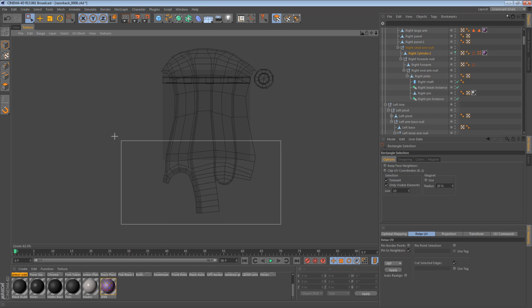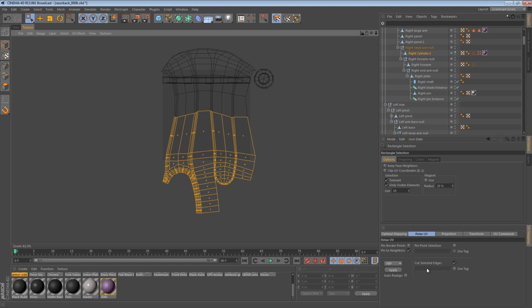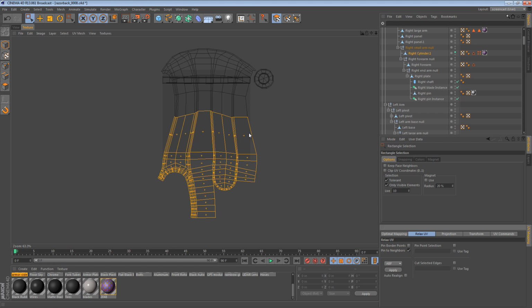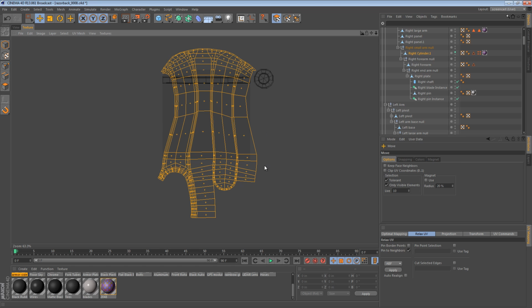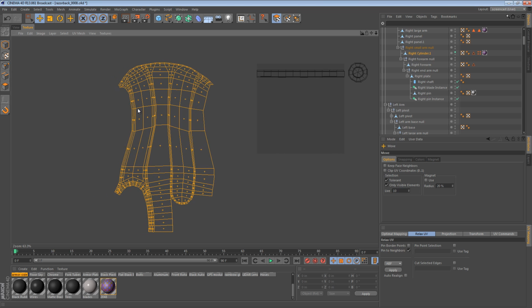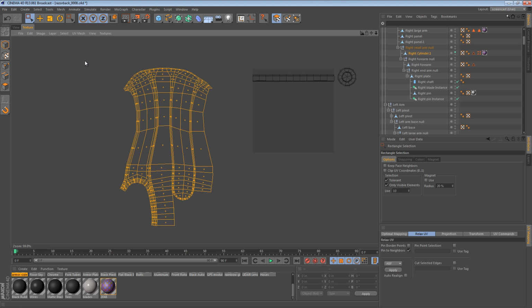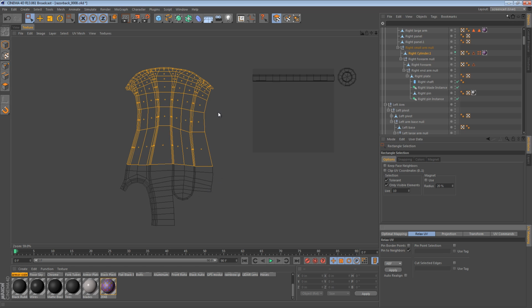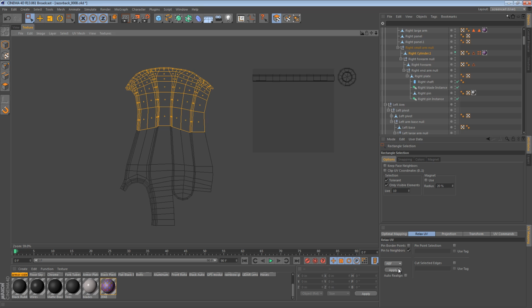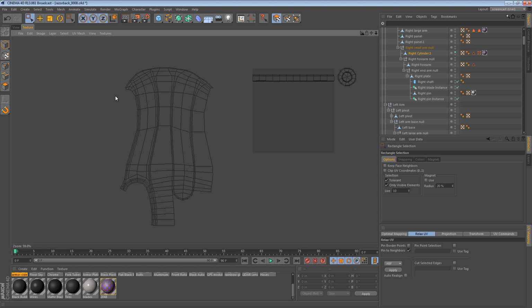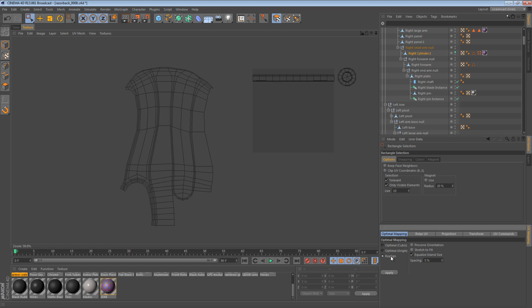And so, you know, at this stage of the game, it's not too late to run the relax command a few more times just to see what happens. Probably don't want to run it on that cylindrical strip we dealt with earlier because we know it's going to curve it. We don't necessarily want it to be curved. So sort of just make sure everything's nice and relaxed. And then we can just pack the UVs in. So we can go to optimal mapping, realign, equalize island size, and we just pack them in there.